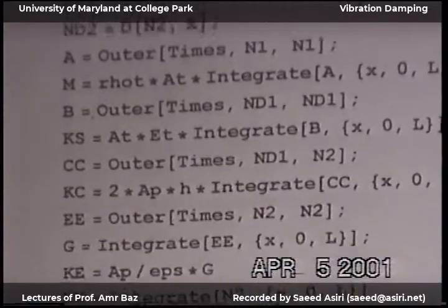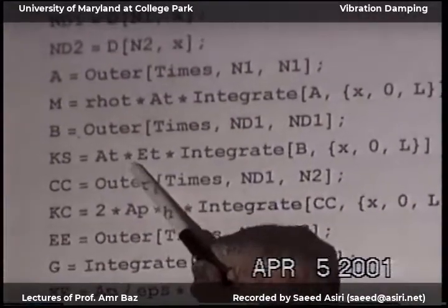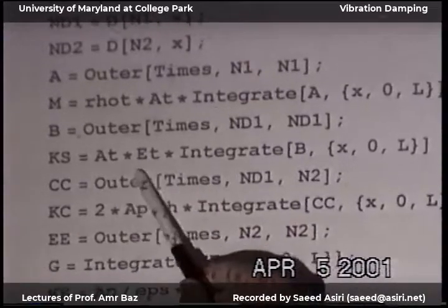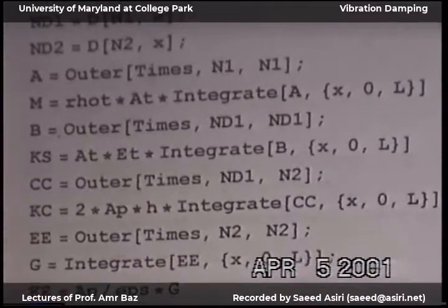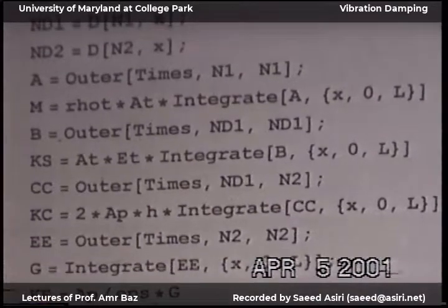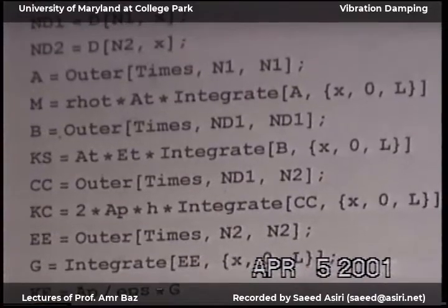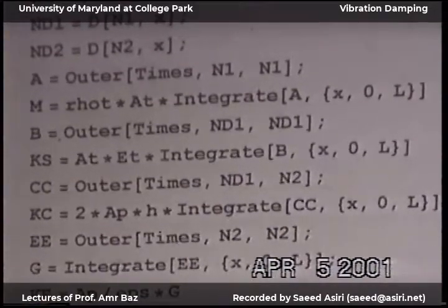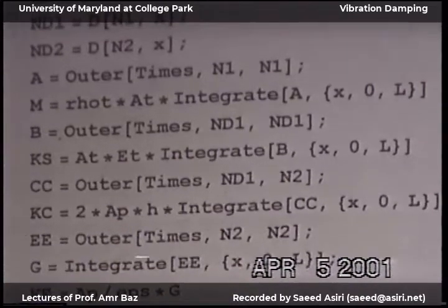And then now we go into the three other matrices. I can calculate the structure matrix, A total, E total, which is the first term. The total area times Young's modulus for the rod and the piezo. And then I need to integrate the derivative of N1 times N1 derivative.